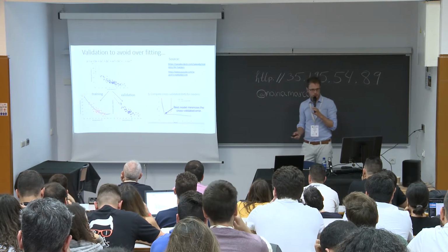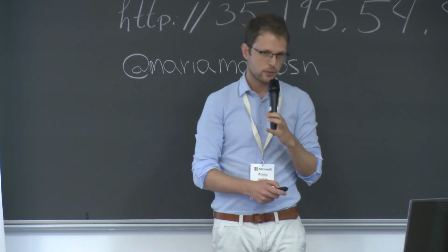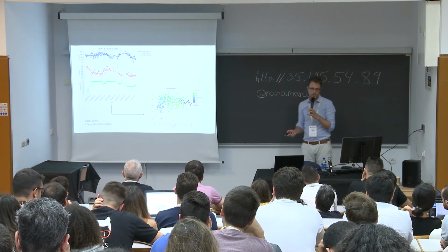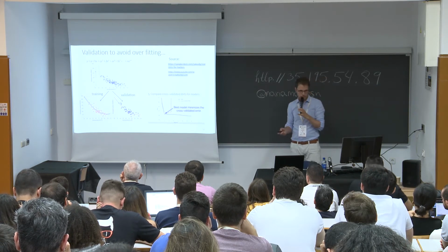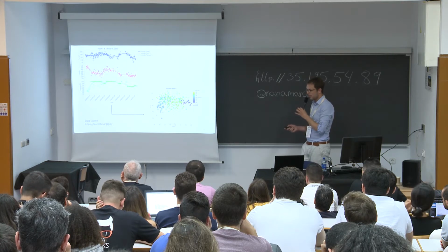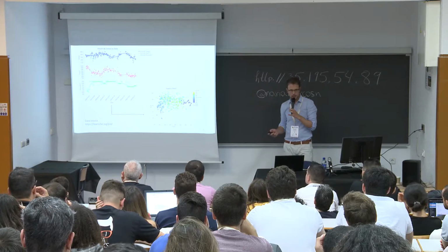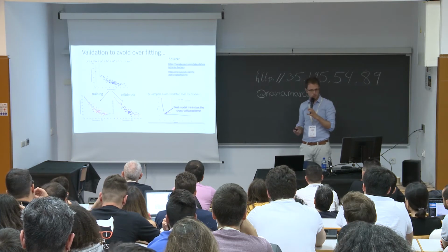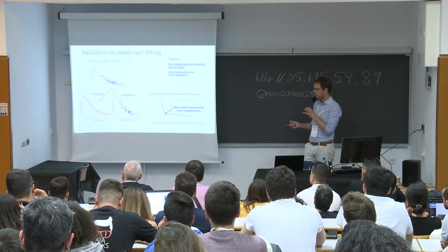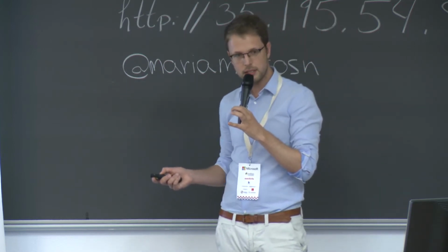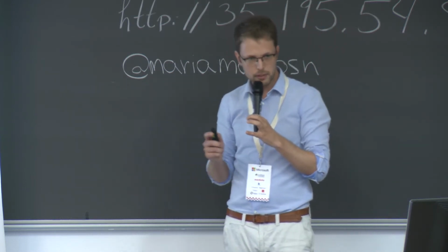But you are probably going to fall into a very, very common mistake, because we know all of that trick of machine learning is about splitting your data, training and validation. But when you're in a time series and you forget there is a dynamic process behind, you're prone to overfit without even knowing. What I mean is, imagine that this process has certain variability, and I have a huge sampling rate. I have data every second. And I'm measuring the pressure and the temperature of a huge tank. And the tank will take a while to cool down or to be heated. So when I do a random split of my data here, training and validation are going to be very, very similar. So if I just use this methodology to validate my modeling, forgetting about the time, forgetting the dynamics, I guarantee you're going to be in trouble and probably you're going to be overfitting.